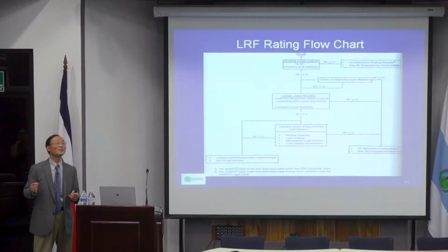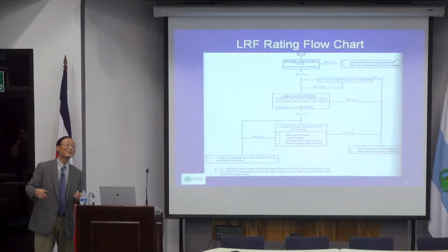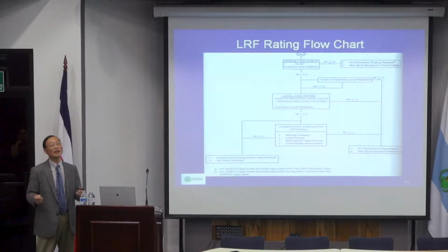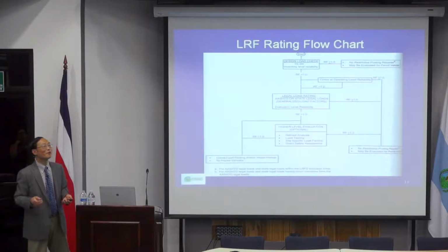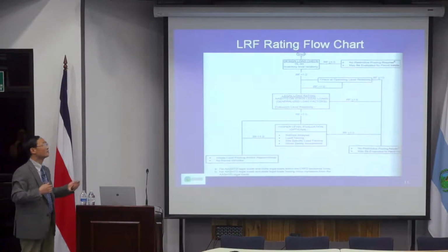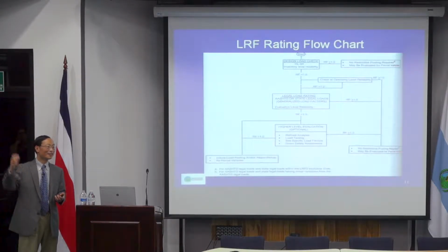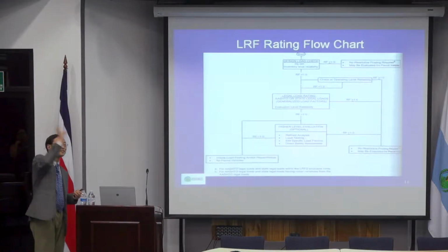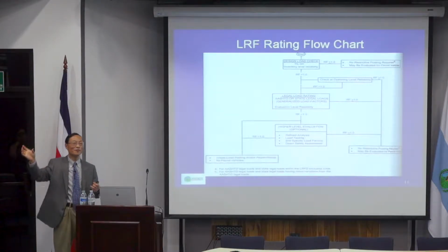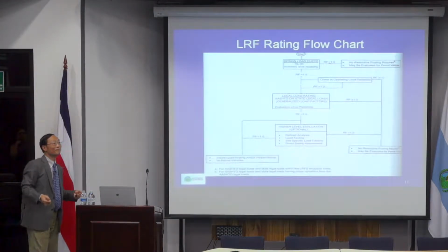Load test is not really just testing the bridge to see how much load it can carry before it collapses. Because if you collapse the bridge, there's no way to save it, so it doesn't serve your purpose. What a load test does, and we'll be discussing that later, is put a load on to see how accurate the model is. Because when we design a bridge, for example, how much live load each girder will carry, percentage-wise, is usually not accurate.